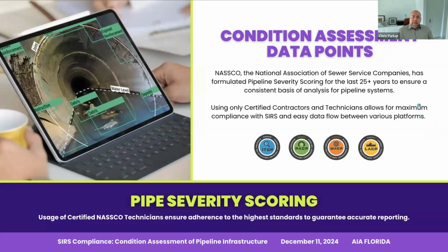And then finally, we get into that pipe severity score that I mentioned. This is a scoring algorithm that is based on a number of variables. It's going to take in coordination the pipe size, the pipe type, the age of the pipe, whether it's a vertical pipe, a horizontal pipe, the material of the pipe, but effectively you're going to get a pipe rating, a likelihood of failure score.